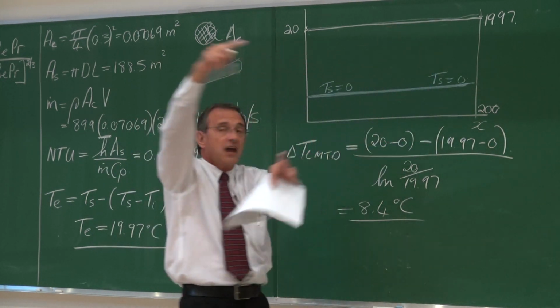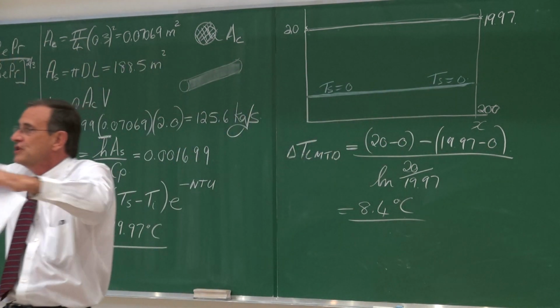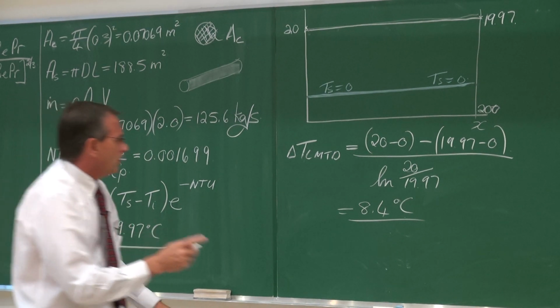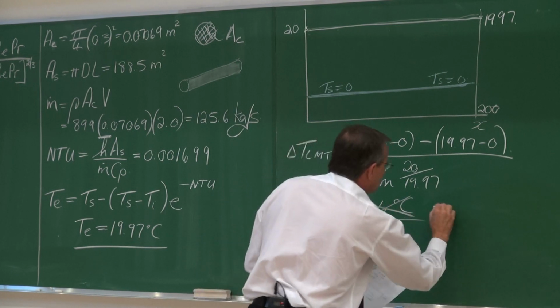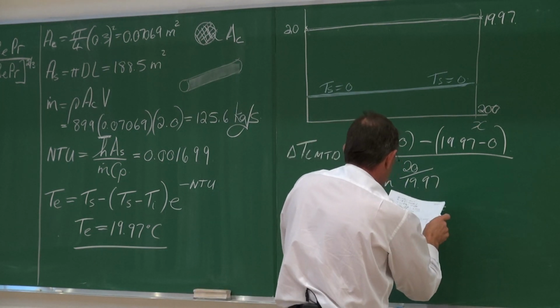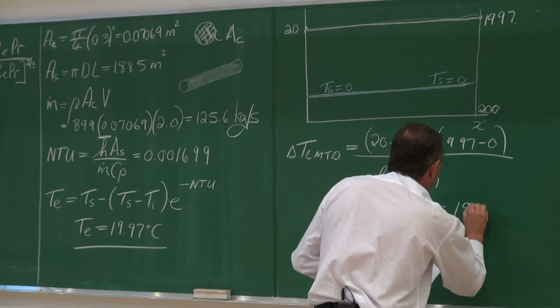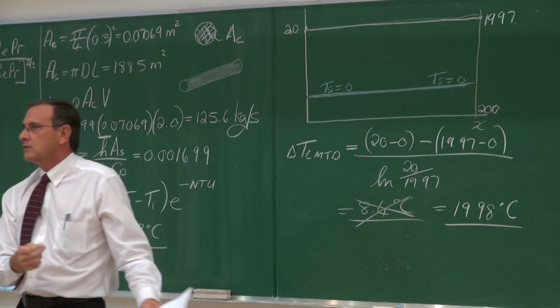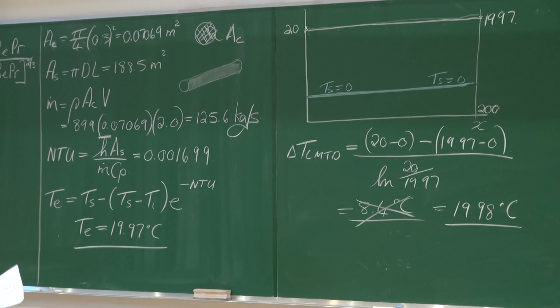What would you say is the average temperature difference between the two streams? It should be approximately 20, isn't it? So I've made a calculation error here. It is actually 19.98. And if you get that, then you should smile, because it means you've most probably done the calculation correctly. So think when you do the calculations. Do not just go through the motions.